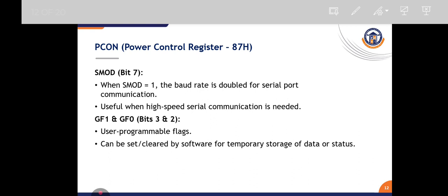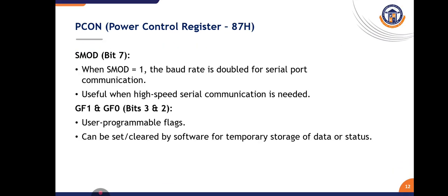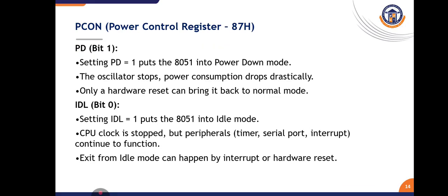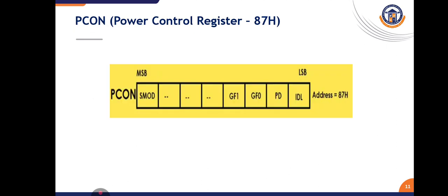And this is the PCON register. This is a power control register which is used in the microcontroller. As the name suggests, it is used to control the microcontroller's power modes, located at address 87H in the SFR space. And the PCON register is not bit addressable.